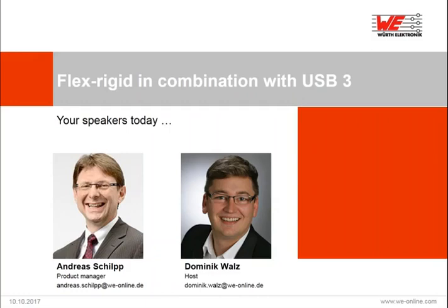Okay, now we have received another question. Is it better to reach the flex layer with USB 3 signals as soon as possible to have better performance? Generally, yes. Short lines are always better than long lines. Of course, losses are smaller, and all other effects like reflections could be reduced. But I think it's more important to have a look at the via technology.